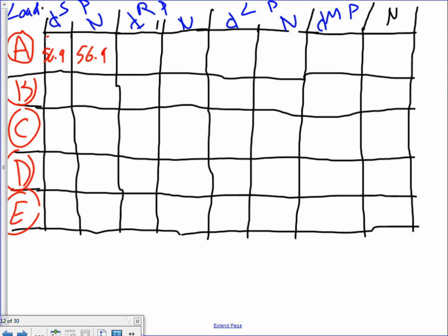Now, do me a favor. So this is the service panel, it will see that load. Which other panel, Derek, will see the load too? The service panel, these are receptacles. Where are you going to feed them from? The receptacle panel. So this will be also 56.9 here and 56.9 here. And what do you guys think here? There will be 0 here, 0 here, 0 here, and 0 here.